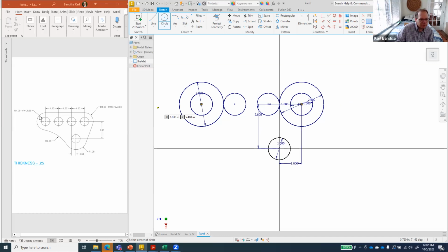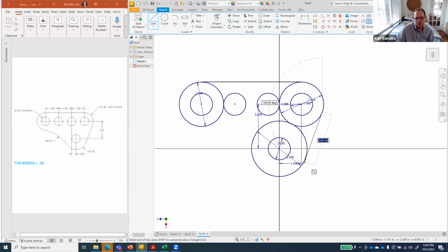So now we have the curve shape here and the curve shape there, which means we can just draw a line. It will automatically select the top of the circle, so that looks good. We can do the same approach for that line right there. Well, we just need to get this curve. Now this is 1.5, so diameter of 2.5. And we can do the same thing. Right? We can have it automatically be tangential. Don't need a second. Right, so we have those lines there.